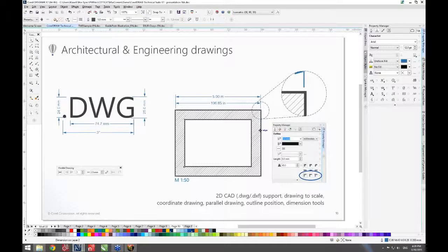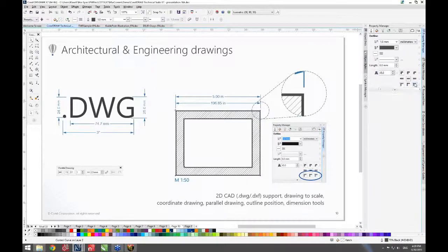And what we can do now in Corel Designer X7 is that we select an outline position, and by making that the inner or inside outline, I have the accurate measurement here. So this layer, simulated or illustrated by a thick line, is now clearly inside the measurement, and that's how you can specify this now with Corel Designer X7.